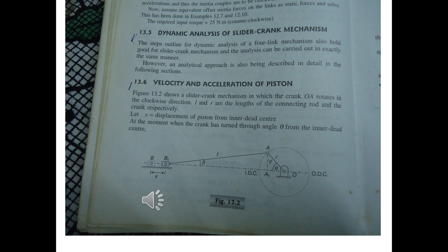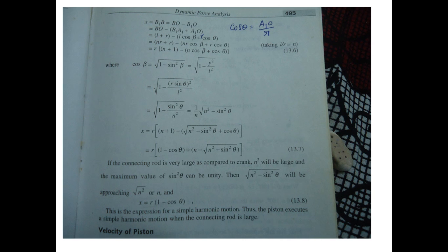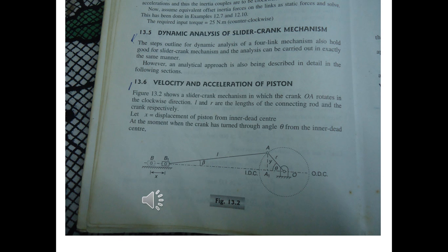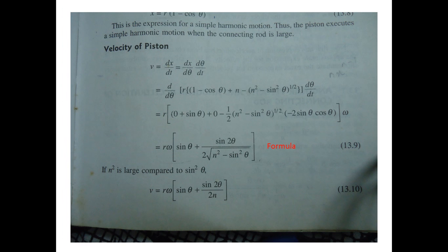Now this particular module on dynamic force analysis consists of a number of formulas for you to memorize, like the velocity of the piston, the acceleration of the piston, and the angular velocity and angular acceleration of the connecting rod. So this is the formula: sin beta is equal to sin theta by n.